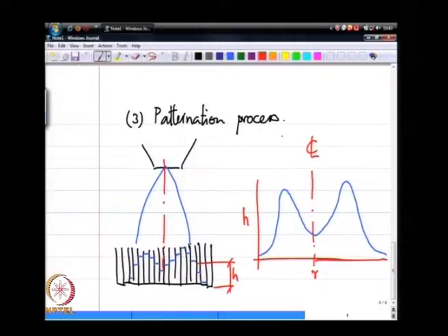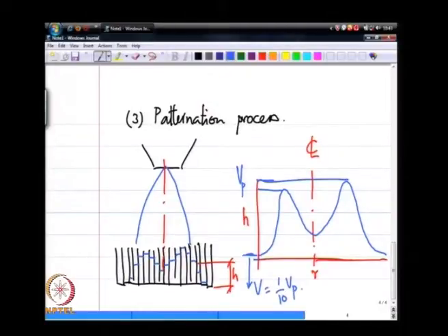From knowing this peak value of the volume flux, and saying, say if this is V peak, I am going to go to a point where the volume flux is 1/10 of the V peak and call that my spray edge. So, the point where the volume flux is 1/10 of Vp is denoted as the spray edge.